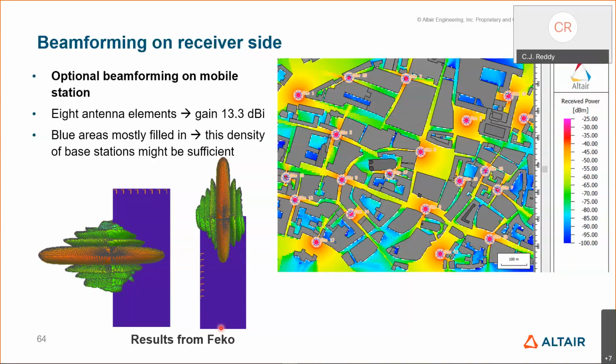So one solution they found, or the solution that came about recently, is what we call characteristic mode analysis. Probably some of you have heard about this term, CMA. What I was told by some of the people who do this kind of work is that when the PCB is done, whatever space is left over is given to an antenna engineer, who is told: this may not be a regularly constructed space, it could be a very arbitrary shape. Go ahead and make your antennas in this space and make sure that they all work, right?